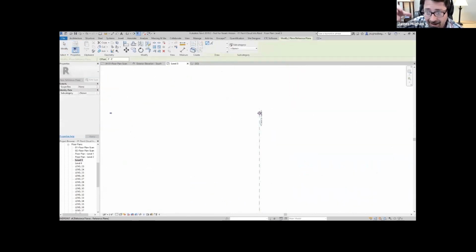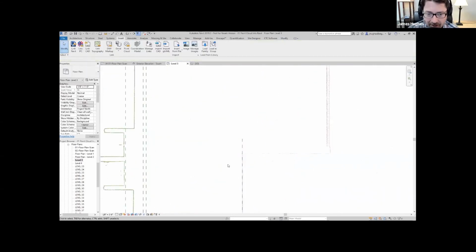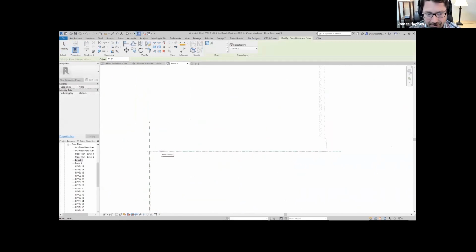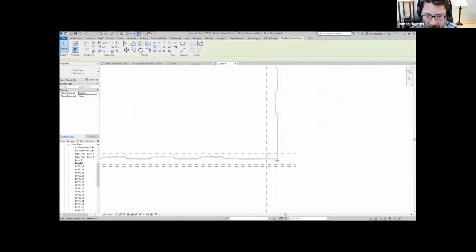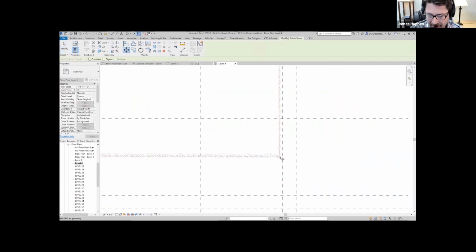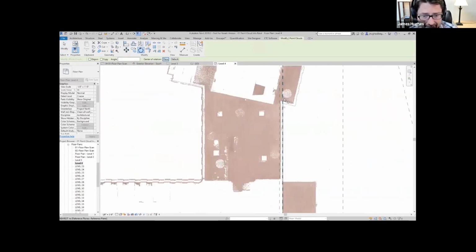As you ascend upwards, the windows were sort of progressing to the north because the building was sinking down to the north, while the reference planes are perfectly plumb. And so it helped us to be able to measure that and come to terms with that. So we can move this corner and more exactly place this 4th floor scan here.